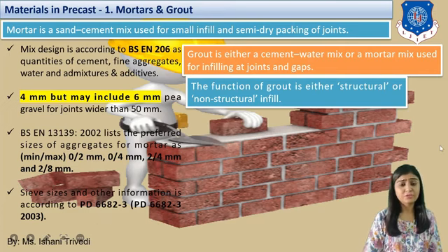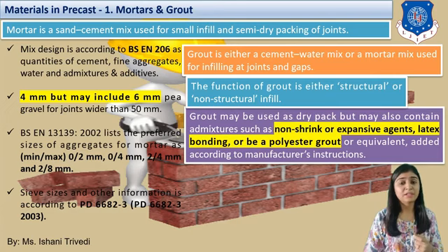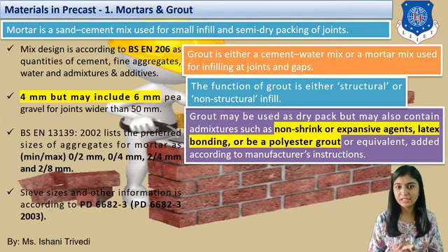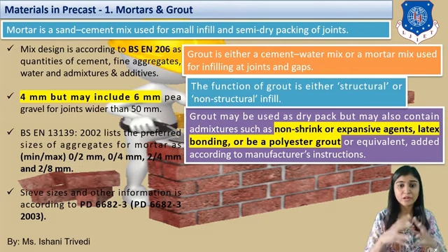Next, we have the function of grout. The main function of grout is to fill the structural or non-structural infill. Now, the structural infill is going to talk about the beams, columns and slab, and the non-structural infill talks about the non-load bearing walls or any other non-structural elements which are not involved in the load transfer mechanism. That is my non-structural elements. Somehow all these elements are going to get clubbed together, they are going to be prefabricated together, and when these joints are to be filled, then grout comes in picture,